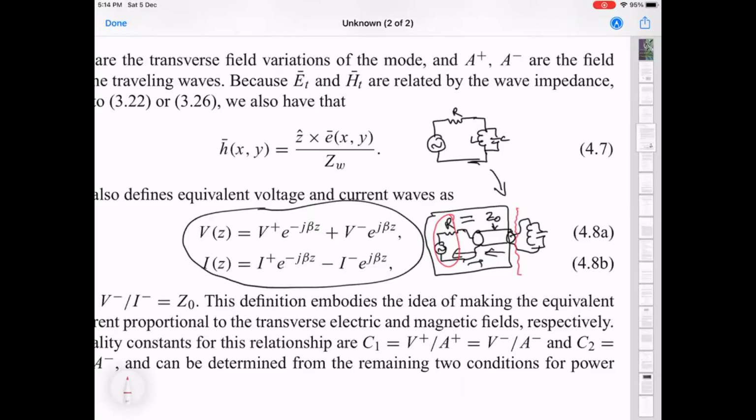I can just compute the reflection coefficient at this point, and that will basically be the same because there's nothing changing here. But if one was interested in figuring out not just a steady state problem, but say the time dynamics of how these waves are going to change in time as you first send out a wave and then it encounters this, then you should be able to write down a differential equation of this circuit, with some subtleties that there are time delays now between what's going on here and what's going on here. But it's this equation which helps you do that.